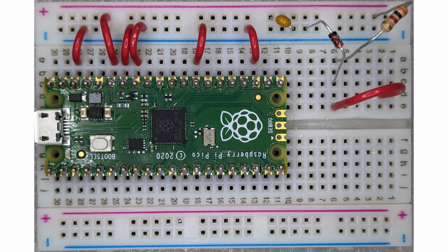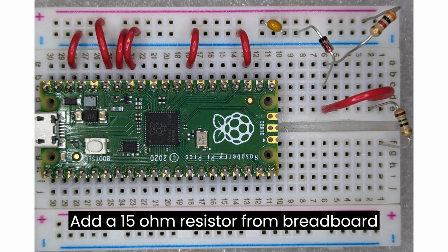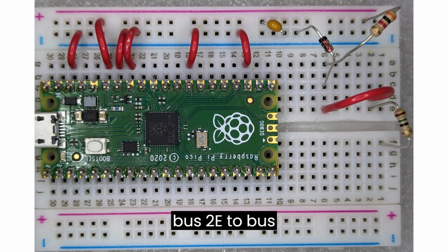This wire is used as a thermal isolator from the 15 ohm resistor. Add a 15 ohm resistor from breadboard bus 2E to bus 1F.